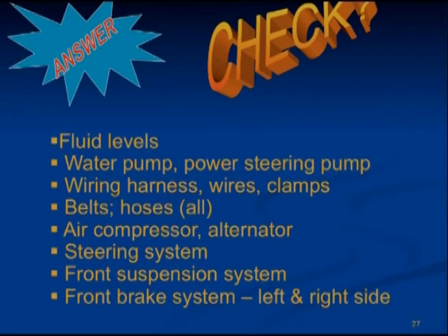Check all the belts and hoses for the power steering, radiator, heater, compressor, and the vacuum pumps. Check your air compressor and the alternator. Check your steering system, the steering column, gearbox, all the linkage, tie rod, and steering axle. Check your front suspension systems, the frame, leaf springs, axle mounts, spring hangers, shackles, and shock absorbers.